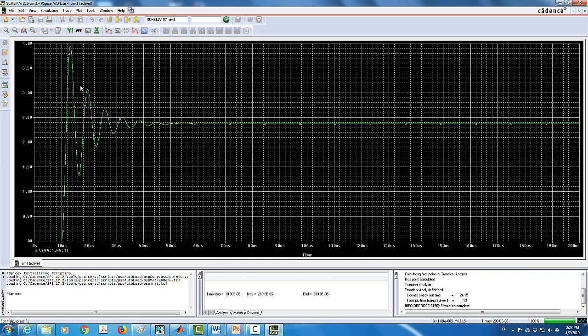And here this frequency is the oscillating frequency, here is the natural frequency. If you wanted to know omega n, measure the time required from one peak to the second peak. What's the time required to go from one peak to the second peak? Then take the reciprocal of that and multiply it by 2 pi. So 2 pi over the time required from one peak to the other peak will give you omega n.